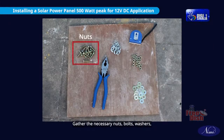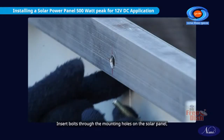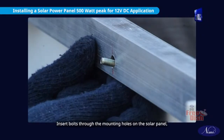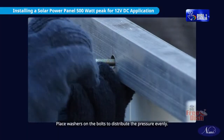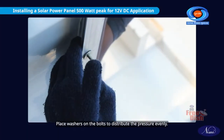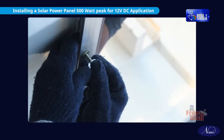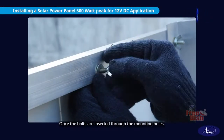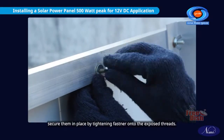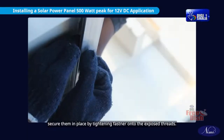Gather the necessary nuts, bolts, washers, and any other hardware required for mounting the solar panel. Insert bolts through the mounting holes on the solar panel, starting from the underside of the panel. Place washers on the bolts to distribute the pressure evenly. Once the bolts are inserted through the mounting holes, secure them in place by tightening the fastener onto the exposed threads.